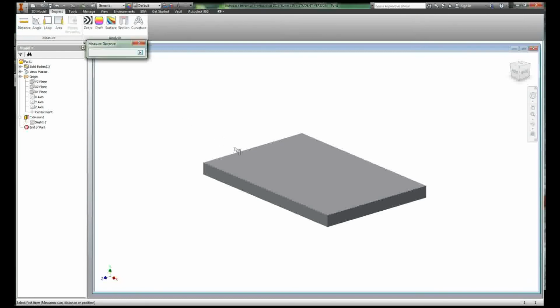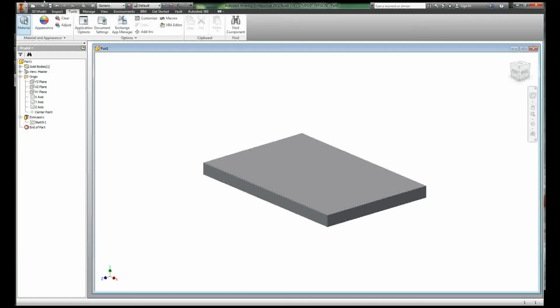You can do measurements of things that you've created if you're not entirely sure how things are. So I just dimensioned this line edge to this edge, and it gave me 10 inches, which is the dimension that you saw me make in the sketch. And the length of this line shows up, that's 15 inches, which is what I just specified. There's a lot of interesting things you can do. You can alter the materials, the appearance.